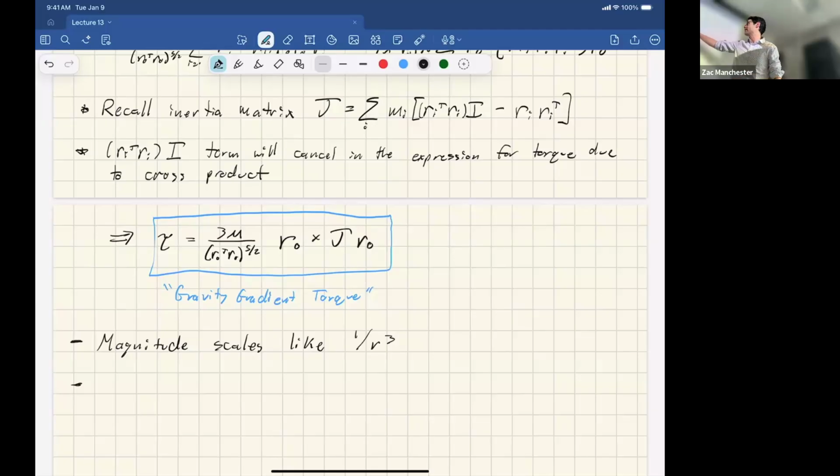So this is saying that when a principal axis of the inertia is lined up with the radial vector for the orbit, i.e., what we were talking about before, the dumbbell, the long skinny axis. So one of the symmetry axes has to be lined up with the orbital radius vector, i.e., pointed nadir down the radial direction. In principle, any of the principal axes could be aligned with the radial vector, and you'll get 0 torque, but not all of them are stable, sort of like the Euler equation situation. Does everyone see that? Makes sense?